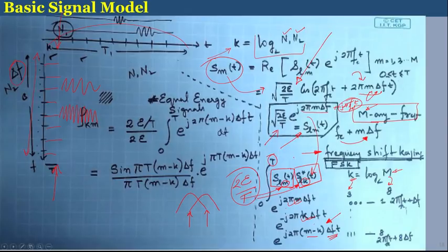Of course, what we have missed out over here is that g(t) should come in. So, g(t) will come in over here, g conjugate (t) would come in over here, and that would result in the mod of g(t) squared, being a scalar number. So, that would appear in each of the multiplicative factors. In this particular expression we have taken g(t) to be rectangular, that means it is 1 in the interval 0 to T. You could also have it normalized.